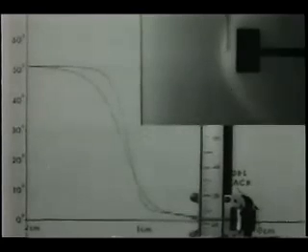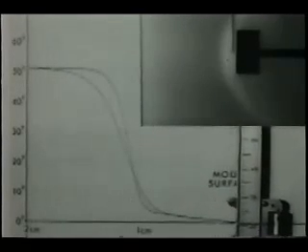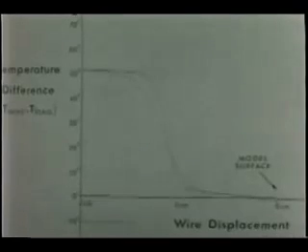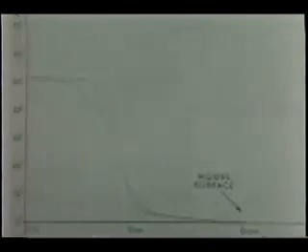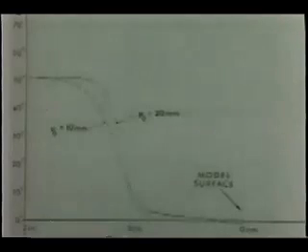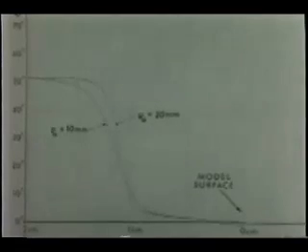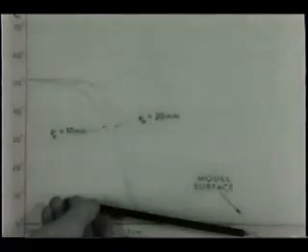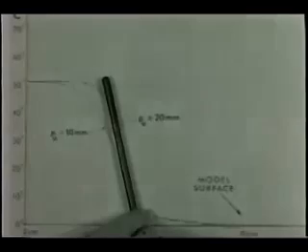Here are the experimental shock wave profiles. The second is clearly not so steep as the first. To define the thickness of the shock profile, we use its upstream and downstream asymptotes and its steepest tangent. Here they are for the first trace. The distance between these two intersections we'll call the shock wave thickness delta. We can do the same for the second trace, and we see that the shock thickness is very nearly inversely proportional to the pressure.